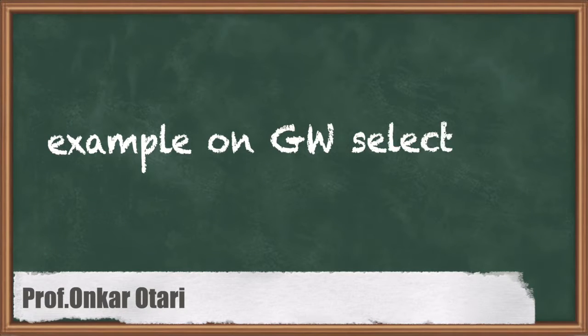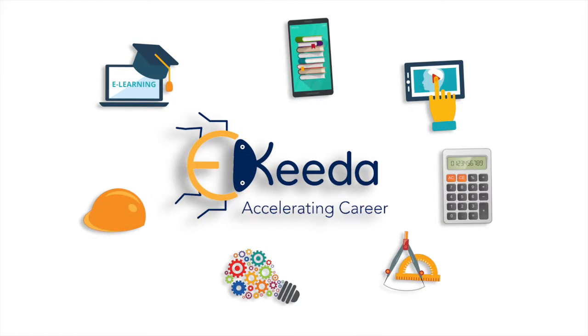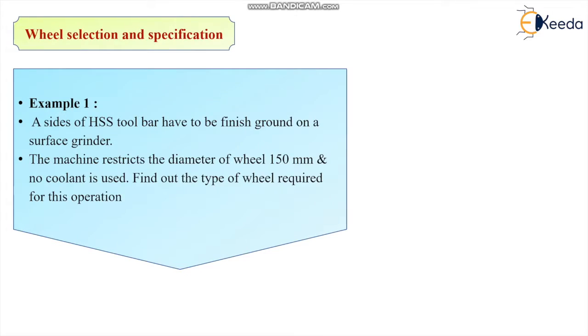So after having the detailed discussion on the specification of the designation of the grinding wheel, let us take one example and we can learn how to select the grinding wheel. Okay, so what is given in the example? Number one, a side of the HSS toolbar has to be finished ground on a surface grinder. The machine restricts the diameter of the wheel to 150 millimeter and no coolant is used. Find out the type of wheel required for the operation.